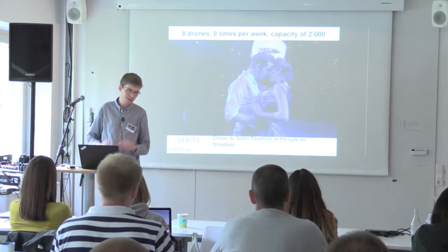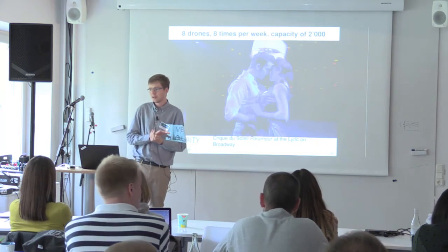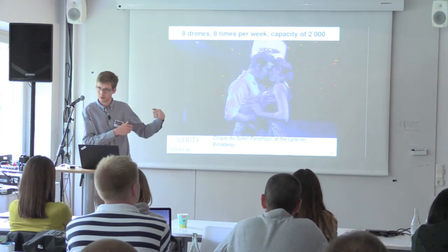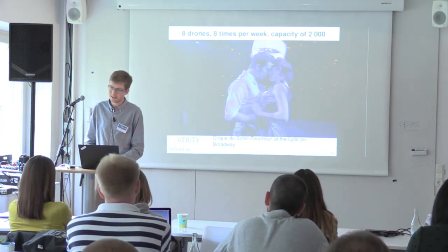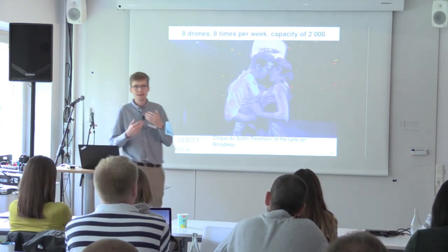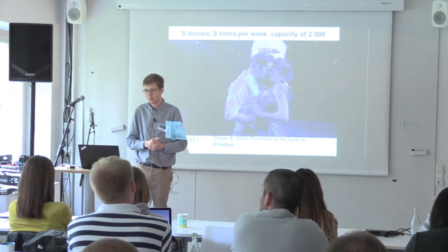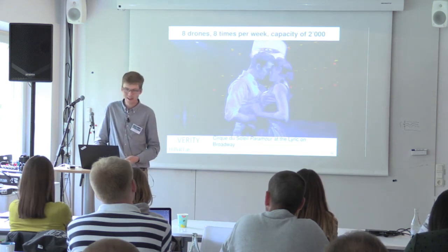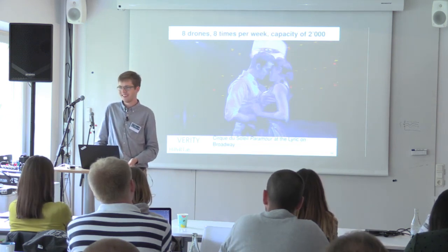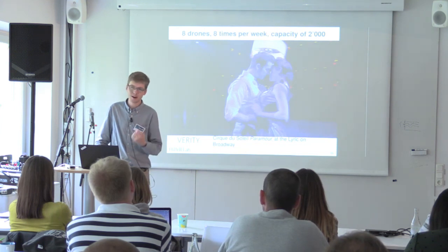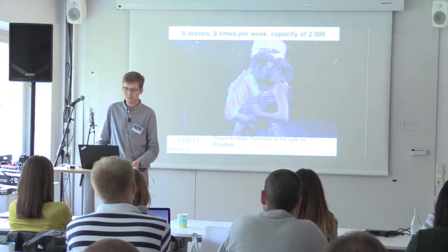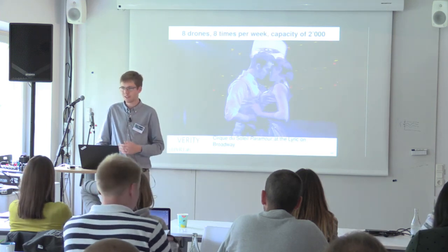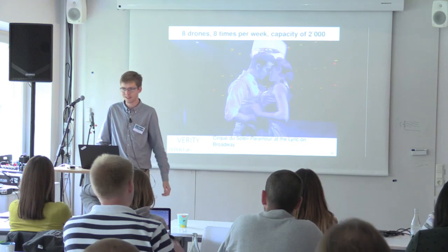But if you imagine having 100, 1,000 drones, then suddenly it becomes a relevant question: is it better to have this centralized approach, or rather something which is decentralized, where each agent reasons about itself and its neighbors? That tends to be something that's very popular in the research. The engineer in me is skeptical of the swarm-like behavior, just because it is so hard to reason about what happens, right? How do failures propagate through the system? How do I reason about safety for such a system? What happens when you have sensor failures, etc.?